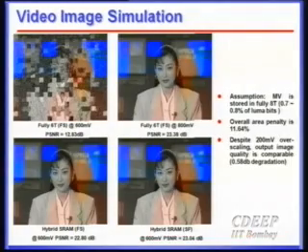But the interesting thing to note is that this is the QCIF format. On the left is fully 6T at 600 millivolts, and there's a huge number of memory failures, which you can see. 6T at 800 millivolts is reasonable. This hybrid memory at 600 millivolts is way better. And this is the hybrid at 600 millivolts at different process corners, the fast process corner and the slow process corner, which is what we looked at. And it shows the image being reasonable.